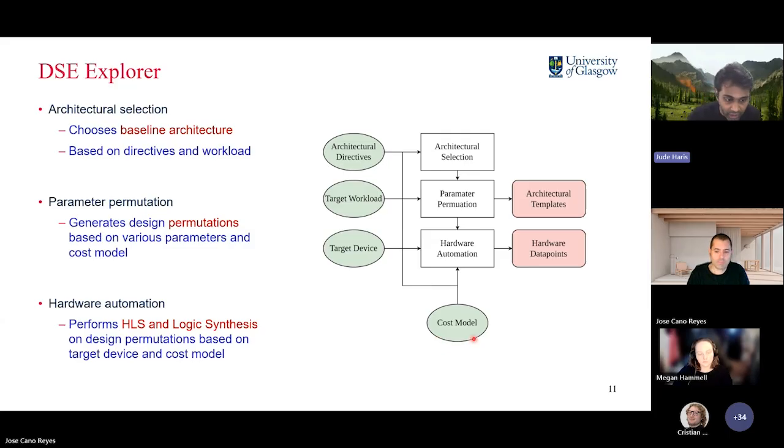The permuted design points are then fed into our hardware automation system, which is where we perform high-level synthesis, simulation, and also logic synthesis to do a simulated evaluation and also an FPGA-based evaluation, and it will get us performance data that we can feed back into the LLM stack. These designs are initially evaluated quickly and packaged as a hardware data point, which is fed into the LLM stack, and also the architectural template itself, not the design points, but the templates themselves are also fed into the LLM stack, so that it has a good context of what the initial